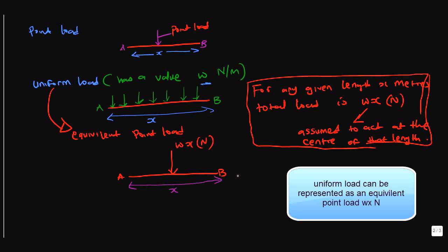Now, if that doesn't make sense, I recommend you do further study on this, or Google it, whatever. But you need to understand this concept. The uniform load can be converted into an equivalent point load acting at the center of the beam.